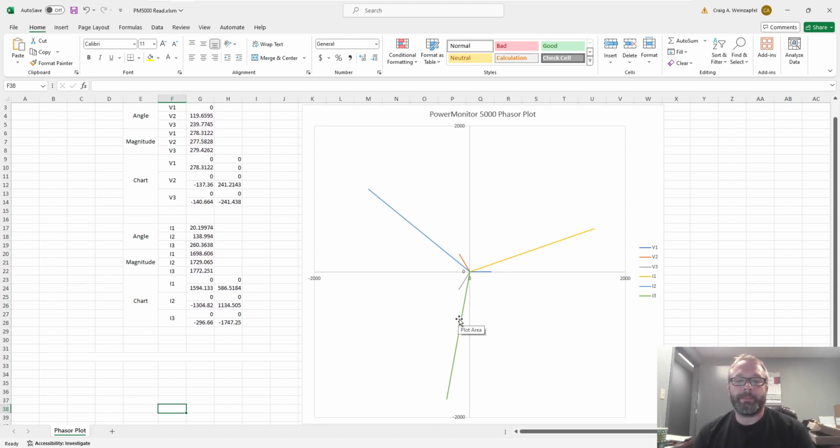So it's kind of a cool little tool. It's the same diagram we would see on one of our harmonic power quality analyzers. To do the same thing, we check our phasors, make sure we're close to spec. It's about 0.94 power factor, something like that. So that made it a little easier knowing this relationship. If you had a really awful power factor, you'd have a larger angle, which makes it a little more difficult to discern. In this case, we were able to figure it out and got it working properly.